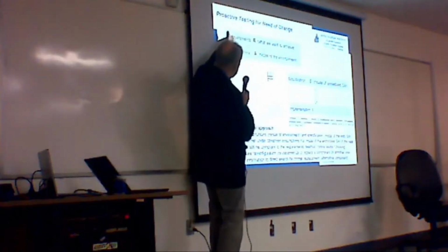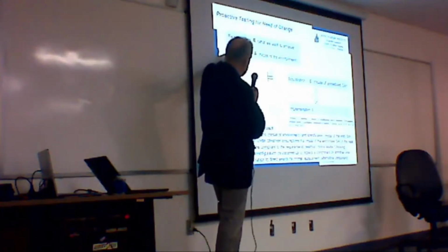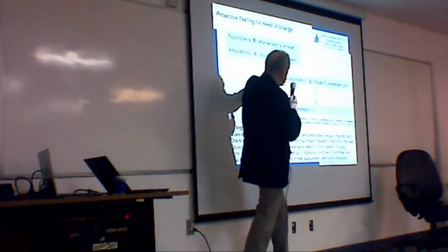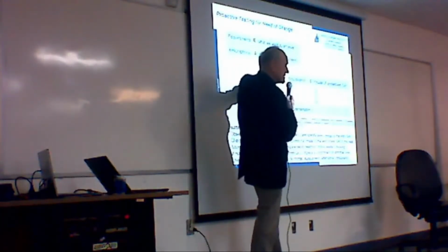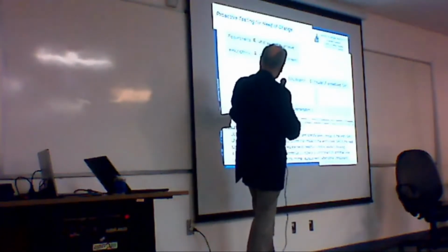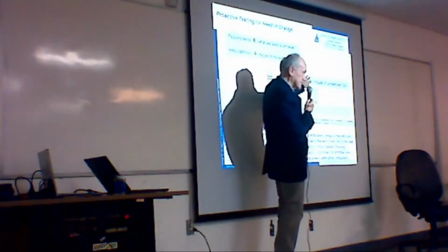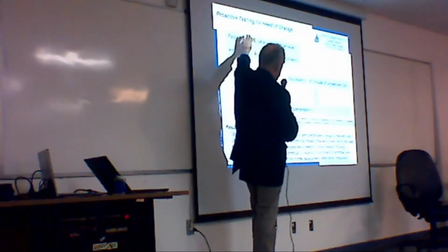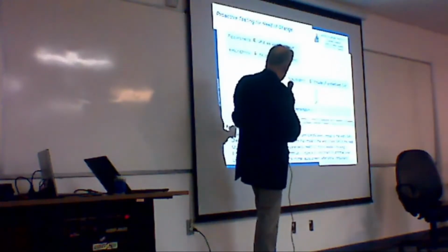So we have our requirements, what we want to achieve, our assumptions, which is nothing else than the model of the environment, and from this we should be able to conclude the specification of our system. And if this fails, the only point where we can play is our specification, the model of the embedded system, as the environment is given, and let's assume at the moment that our requirements have to be fixed as well.